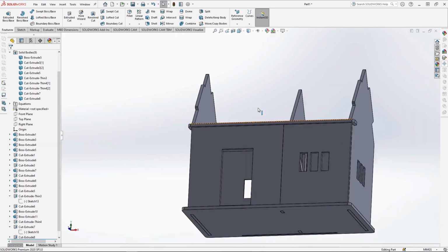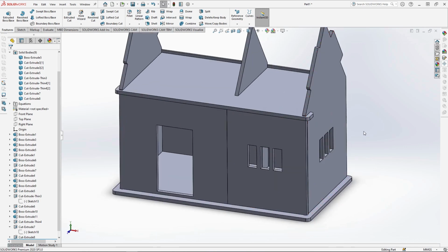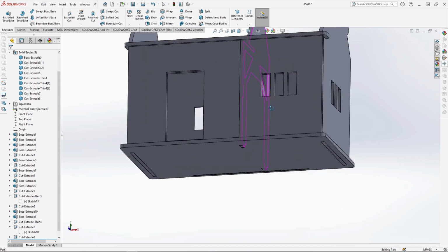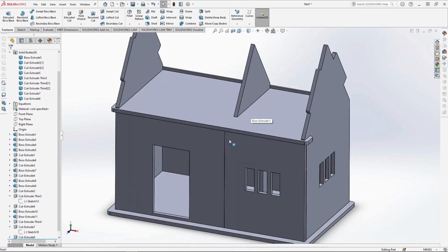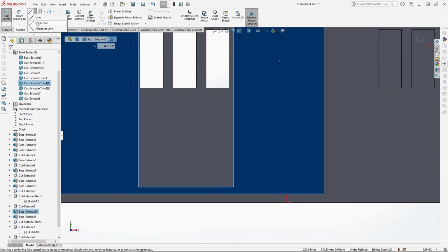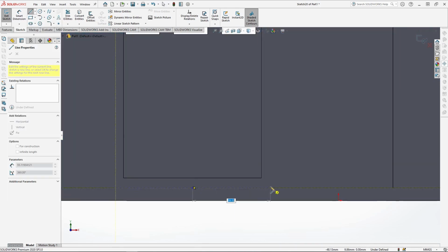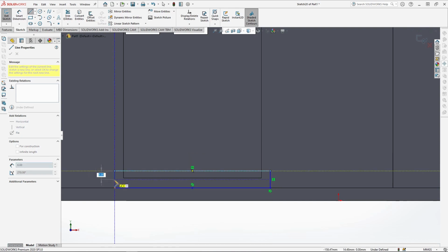Next is the doll's front door details. To hold a door in place using a pole, I need to create a door step and canopy that the pole will sit into. Sketching onto the large front door. Use the midpoint line and find the centre of the door cut out. Follow the smart guides down to the base panel edge and draw the line to 55mm and go up by 12mm and create a rectangle.